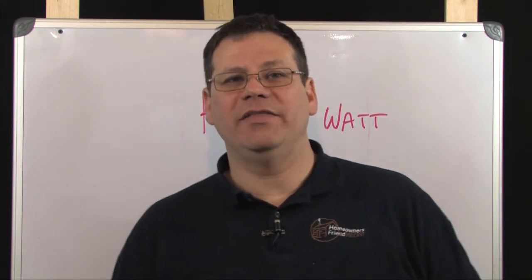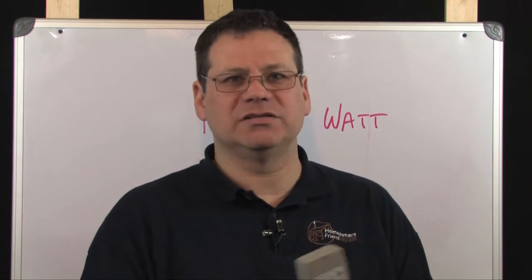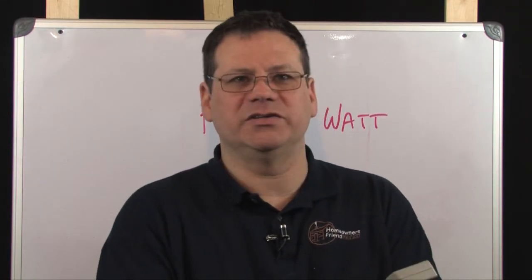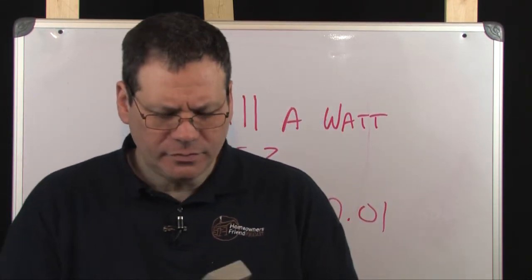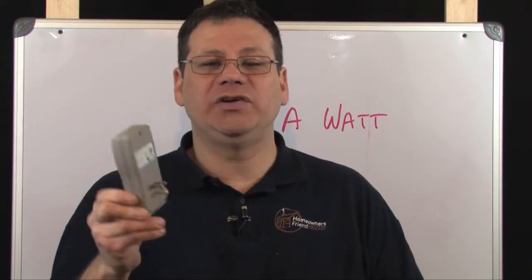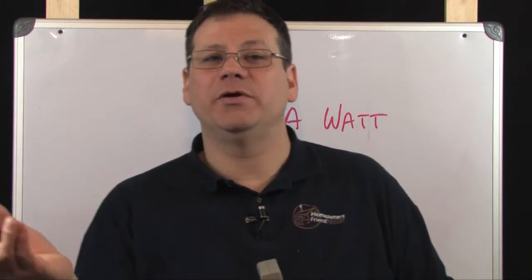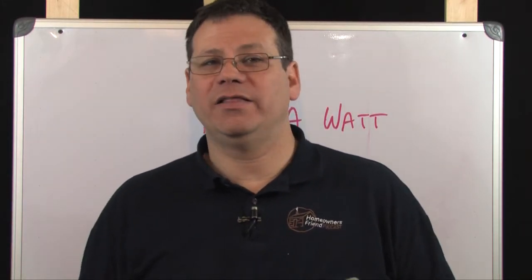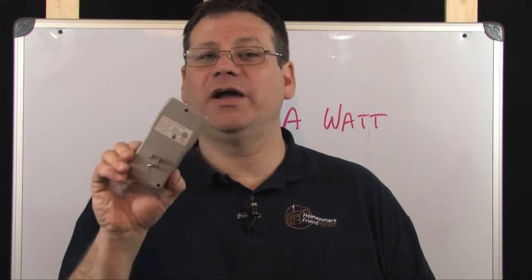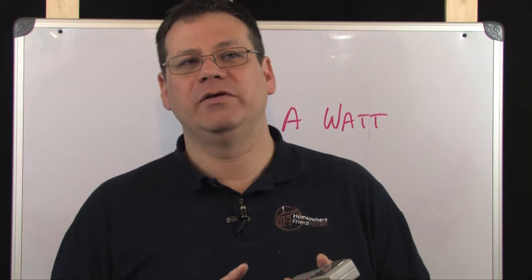And the idle current on these things is really low these days. They've really improved that, so it uses less electricity when it sits there. It's part of the Energy Star rating. So these are really cool, and I recommend getting one. Downsides to these, you can't really measure something that doesn't have a plug on it unless you put a plug on it. For example, your furnace. The furnace is directly hardwired, and it's only 120 volts. It doesn't do 220. So you can't measure things like your electric stove.